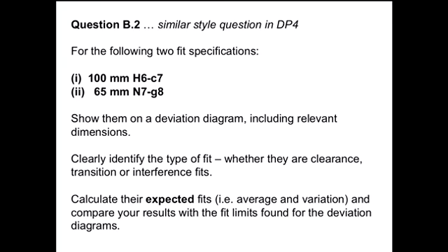Type of fit: look, the student that just says, "Table, number, boxes, numbers on edge of the boxes, finished, move on," gets half marks. You've got to demonstrate you understand what it is and why you've done it. And one of the ways of understanding is, what type of fit is it? Clearance, transition, or interference. And this idea of expected fit, the mean and variation, further indicates that you understand why you've even bothered to get those little boxes of tolerance produced.